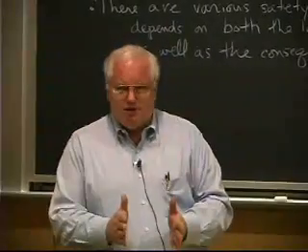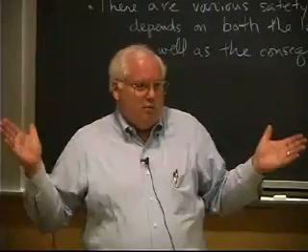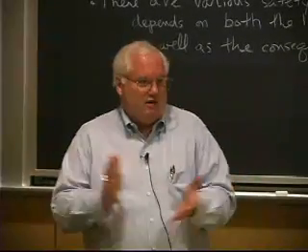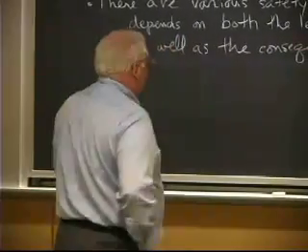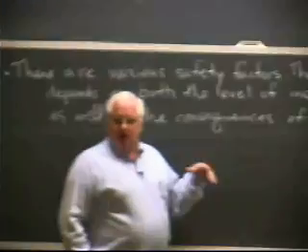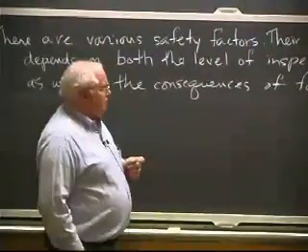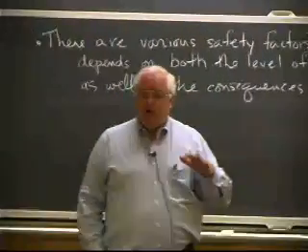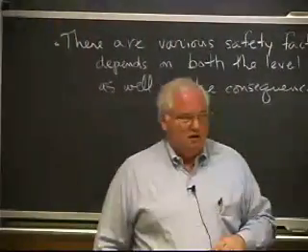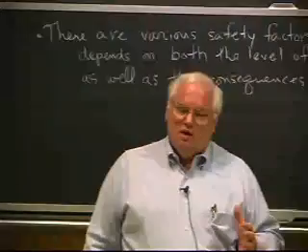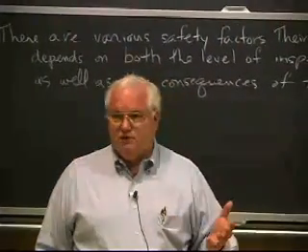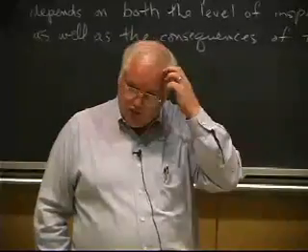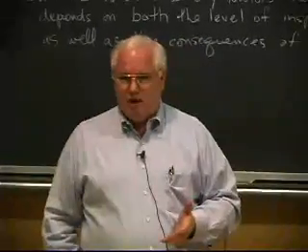However, if you're making bricks for a building, 3 sigma may be good enough. I mean, what do you care if you get one defective brick out of 1,000? It doesn't really matter. Bricks aren't that valuable, and a single brick is not going to have a big consequence of failure if it cracked. However, with a Hubble telescope, if you end up using the wrong geometry or whatever, and it costs you $1 billion to fix, or if a lot of people are going to die, the consequences are such that you want to have a higher level of inspection.